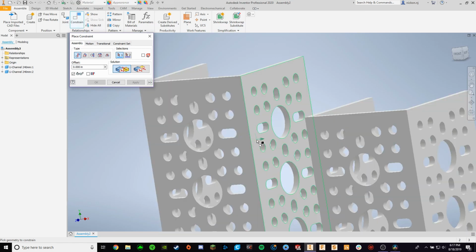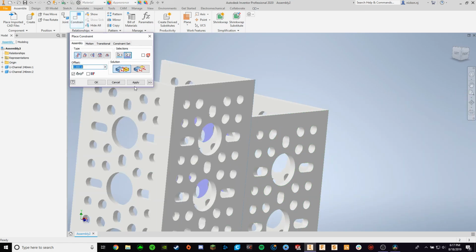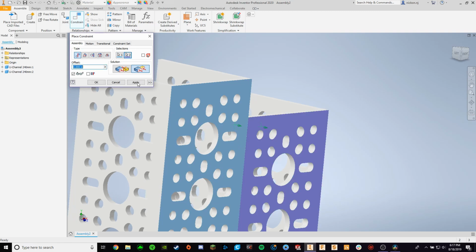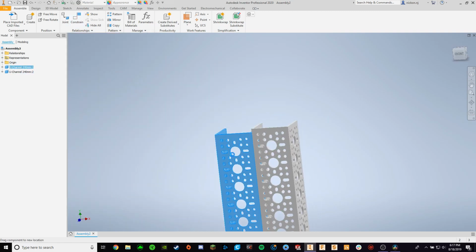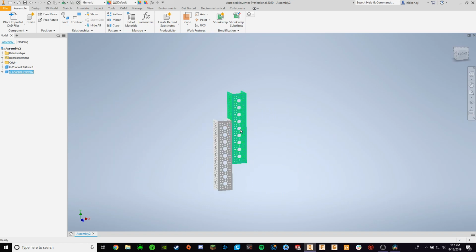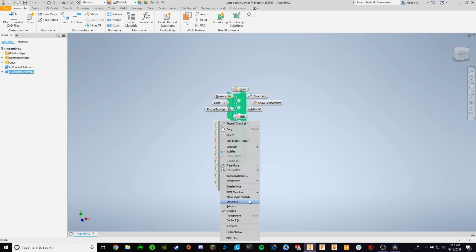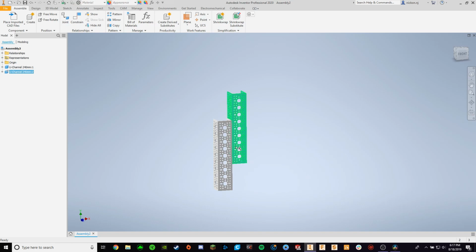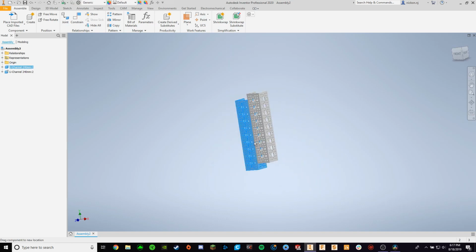If we constrain two parts together, let's do that. Let's get a flush going. So this is the sliding thing again. I can move both of these together, and you might have seen me click this. There's a grounded tool, and now basically what happens is this piece won't move no matter what, which makes the sliding animation thing a lot easier to show.